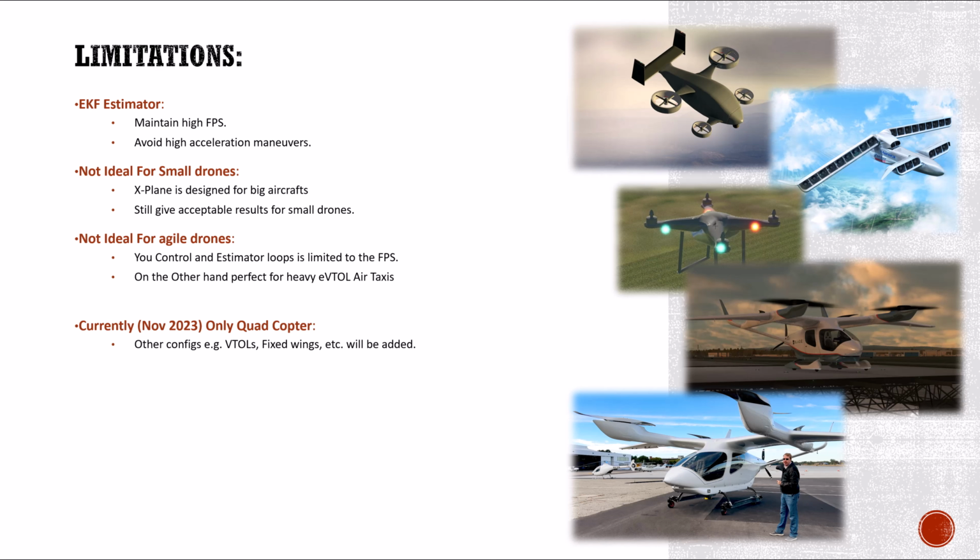Let's now look at some current limitations of the PX4 X-Plane plugin. As I said, it's not the best choice for all applications. First, the EKF or Extended Kalman Filter estimator requires maintaining a high frame rate, especially in scenarios involving high acceleration maneuvers. Then X-Plane is primarily designed for larger aircraft, which means it's not ideal for very small drones. However, this still gives very acceptable and good results. Agile and acrobatic drones are another area where X-Plane might face limitations. Your control and estimator loops are limited to the simulator's frame rate.